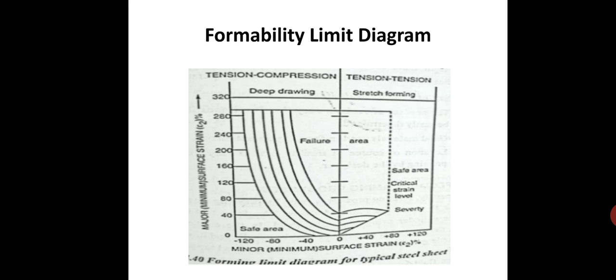The strain distribution is assessed from the surface, but the magnitude of strain is determined by impregnating the sheet metal with a rigid pattern or concentric circles, followed by the pressing.